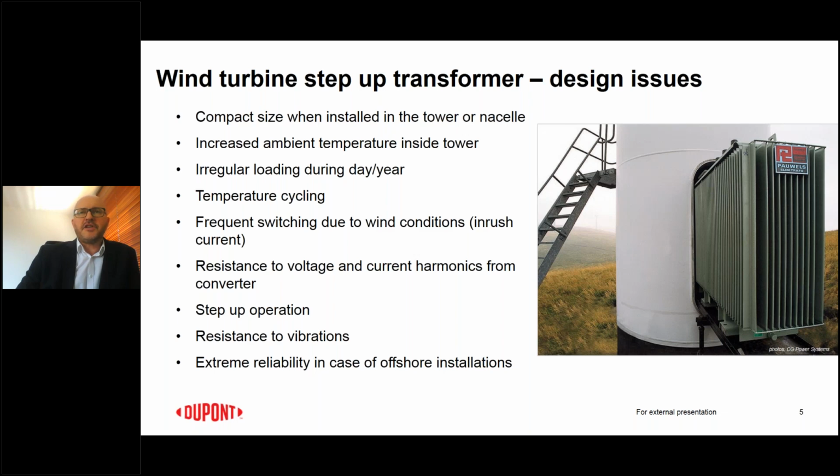Definitely the frequent switching: depending on the wind conditions, the transformer could be switched on and off, which increased the inrush current activity in such transformers, and the need for these transformers to be resistant to the inrush currents, and also the harmonics, whether voltage or current harmonics, coming from the inverter system in the turbine electrical system.